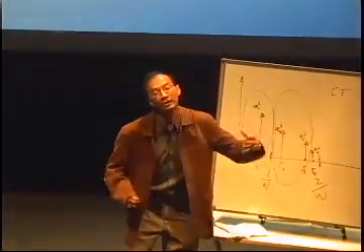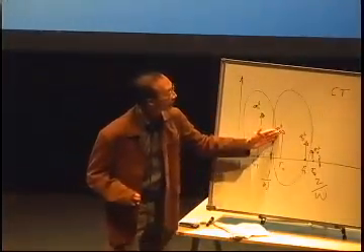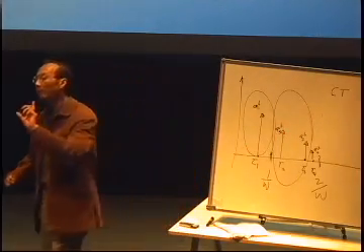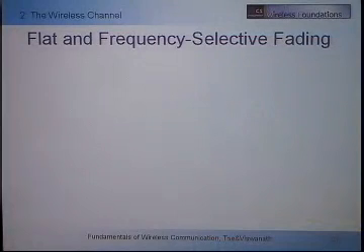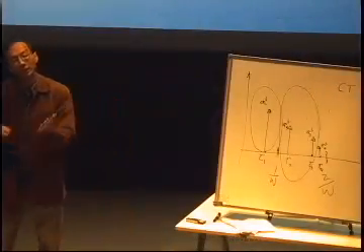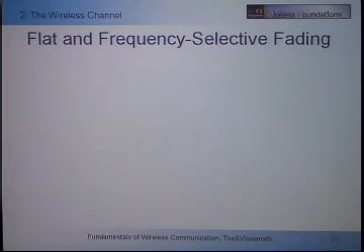And what happens is that if they happen to be 180 degrees out of phase, then each of them may be a strong signal, but they cancel each other, and what we see is a deep valley. So that's a very important point I want to mention: fading, which is the issue that a wireless communication engineer is most afraid of, is because of the bandwidth limitation.